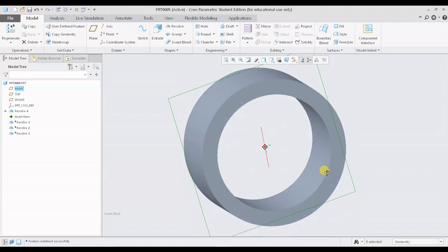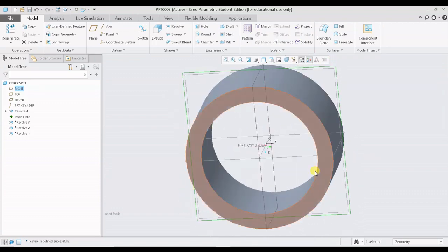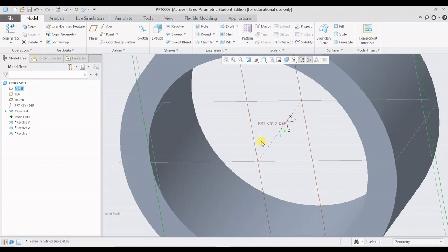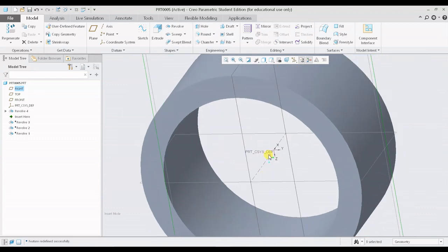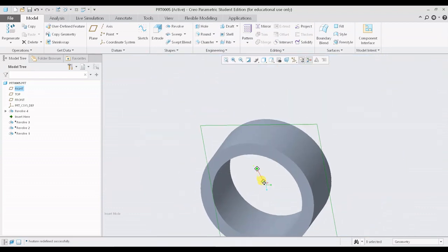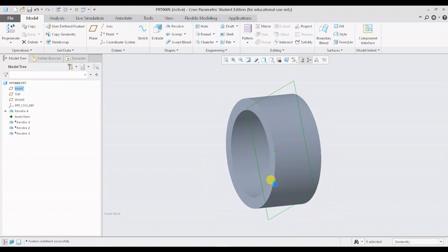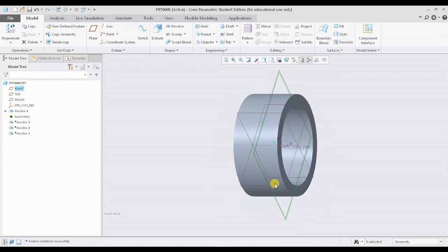And you can see that we have created the revolve, which is having some distance from the axis of revolution. So this is the axis of revolution, and you can see the axis is created over here, and we got this particular ring over here. And this is the way to create or to use revolve command using different options. Let us move to the next video and see further creation of revolve in combination with extrude command.